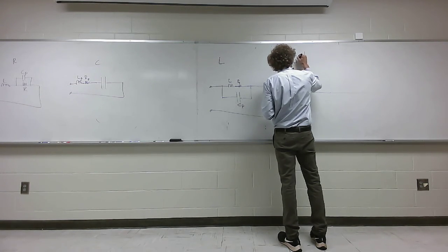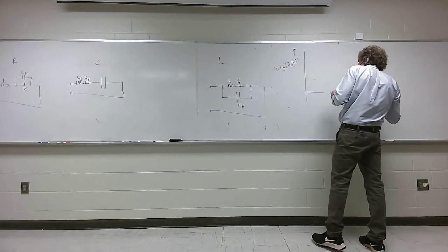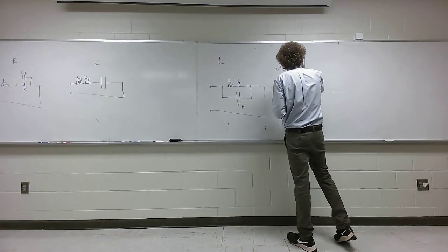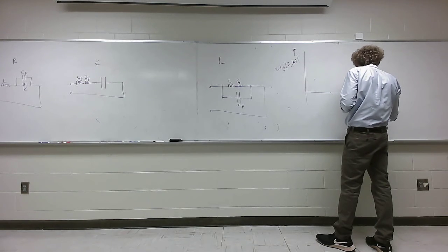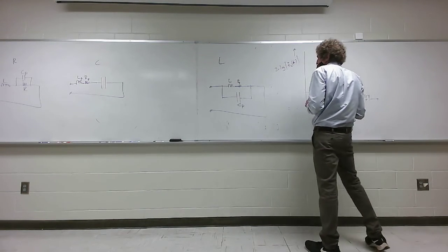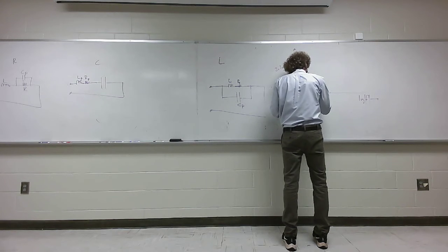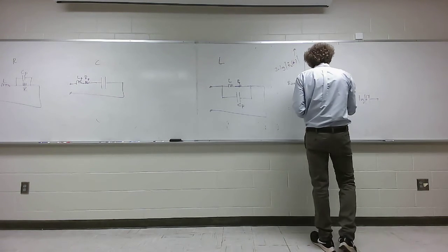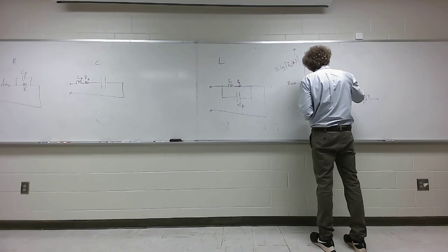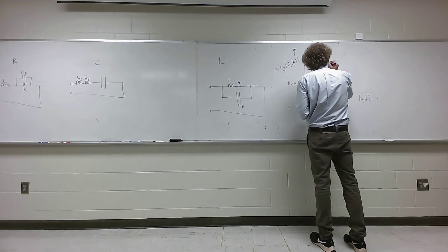versus omega, actually I can put it versus F here, because Wentworth's book will do F, and this would be log of F here. You will get something that's very, very low impedance here, and this is going to be something associated with just R of the wire, the DC resistance. Then there'll come a point and it'll start going up at plus 20 dB per decade.